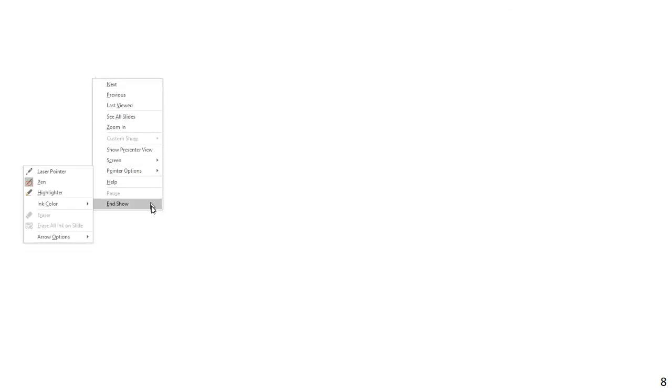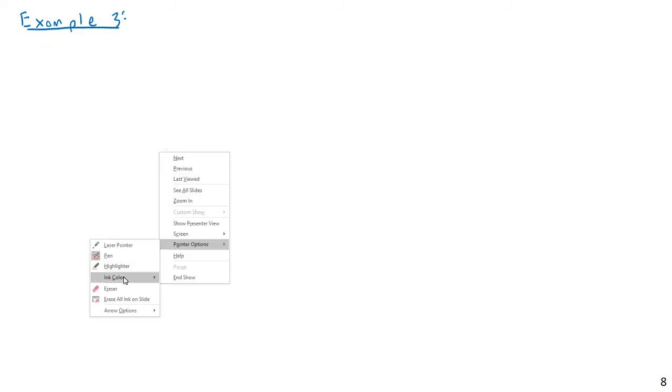So let's work through a hinge example. And this is going to be interesting because we're actually going to need two free body diagrams. Let's call this example 3. So consider this beam here. This is going to be a fairly interesting beam in that we're going to have more than 3 reactions. In fact, because we have a hinge, we need more than 3 reactions for this thing to be stable.